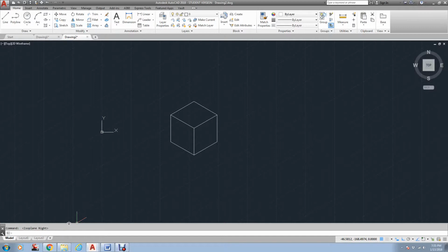Understanding that they each have an opposite side, but in doing an isometric, there's really only three planes you need to work on, which are those three: left, right, and top. Really, one of them should be front, but that's AutoCAD's problem, not mine. Now, whenever you're working with these, you can change the plane you're working on while you're in the command.